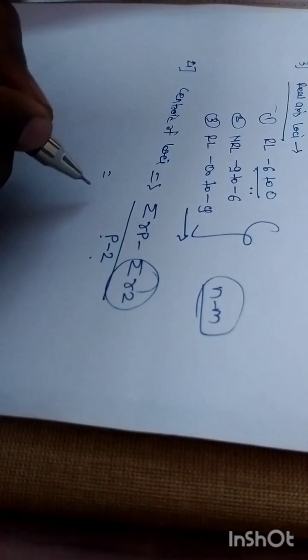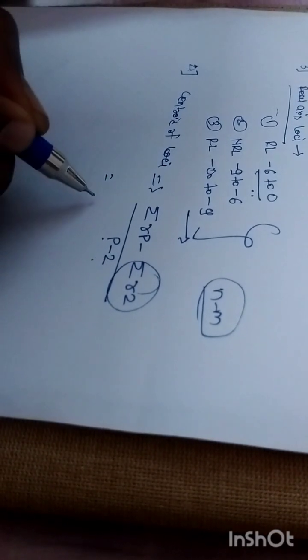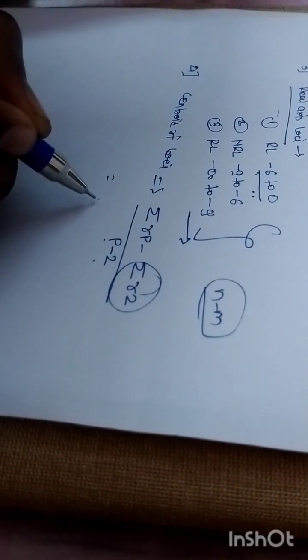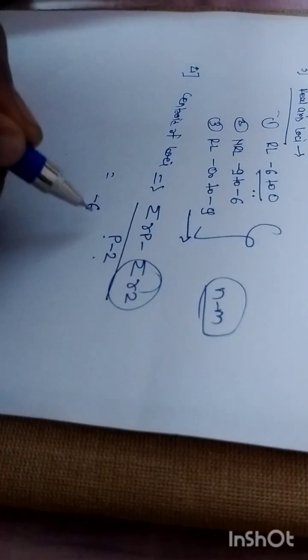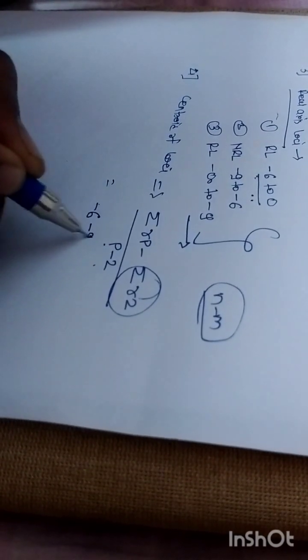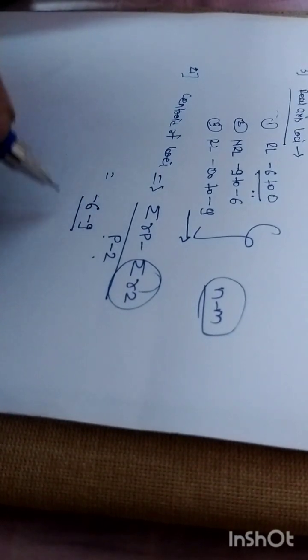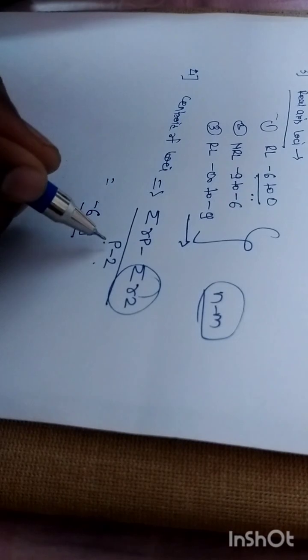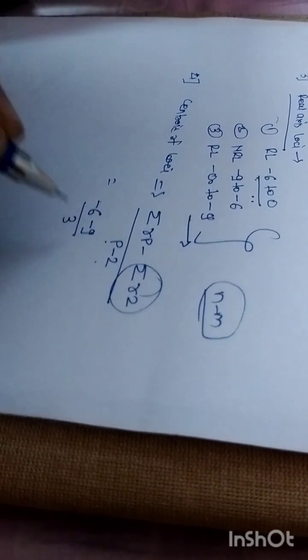One pole is located at the origin, right? Apart from that, another pole is located at minus 6, so the summation of the real parts of the poles includes minus 6. Another pole is located at minus 9. So minus 6 minus 9, and the denominator will become P minus Z, meaning the number of poles minus the number of zeros, so it will become 3.